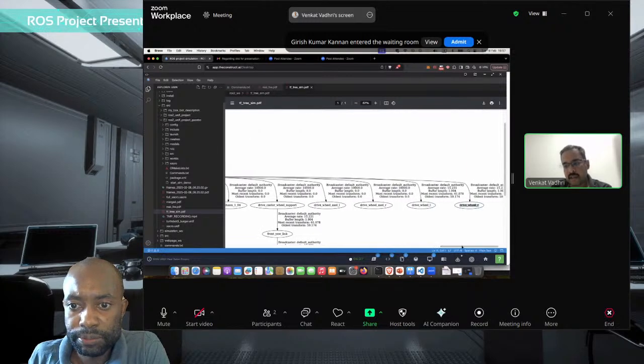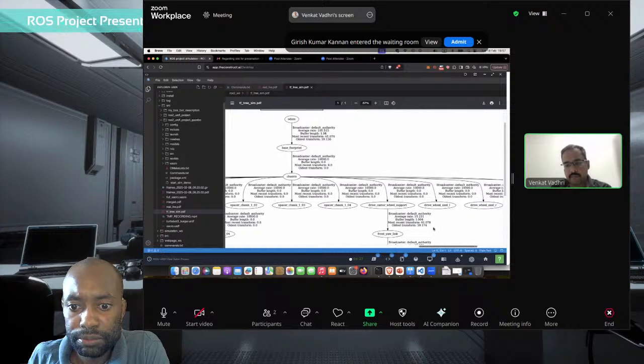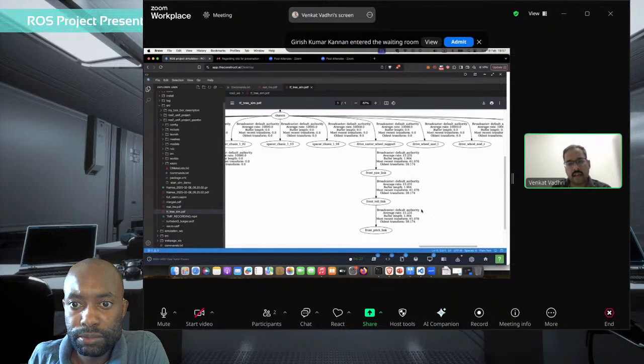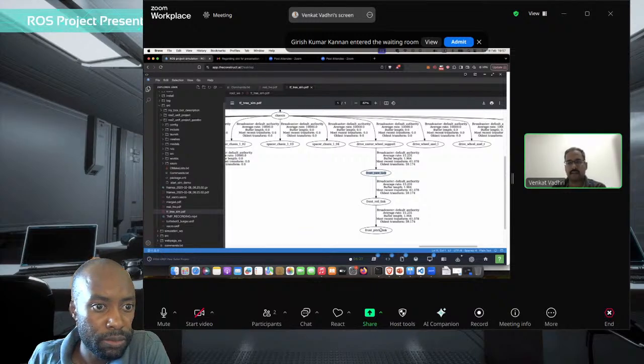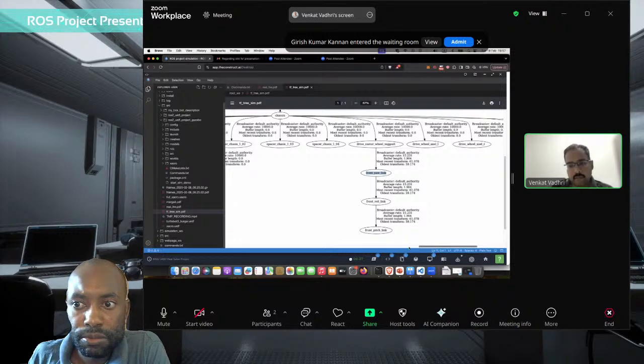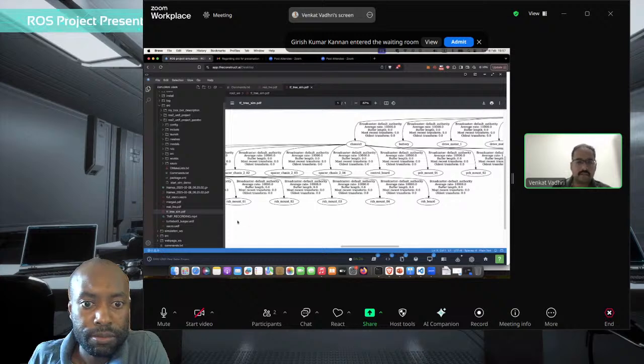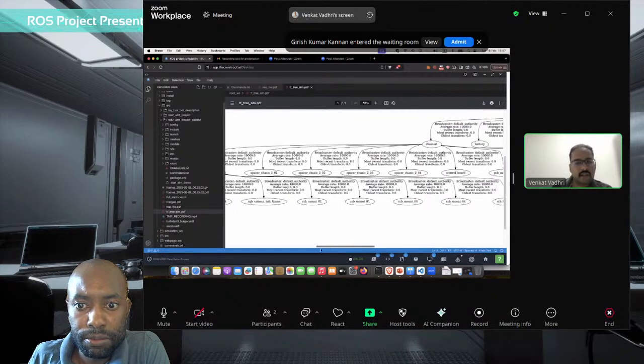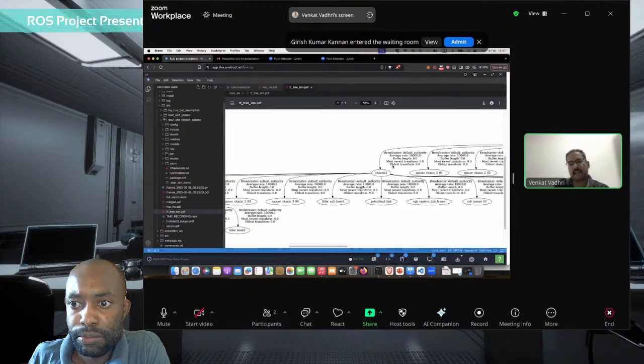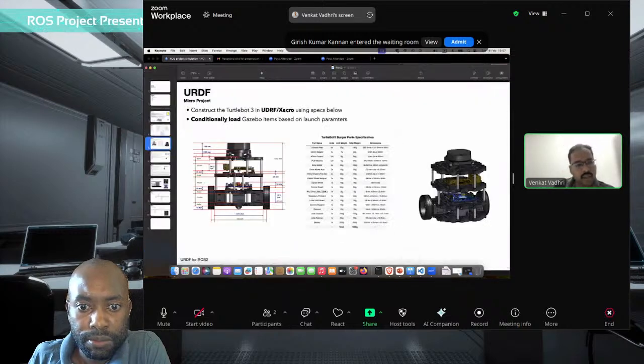These are the side wheels, and in the front there is a wheel that is actually rotating in 3 different dimensions. The way we combine that is we have a yaw link, a roll link, and a pitch link, and put them in the same place and connected one after another. And these are all linked to the chassis. Now you can see that chassis 1 is linked to chassis 2, and whatever is inside that specific chassis is connected to it. So just to put a picture to that statement: if there is a board here, this board was connected to this chassis, and this chassis is connected to this chassis. So I connected a tree like that.